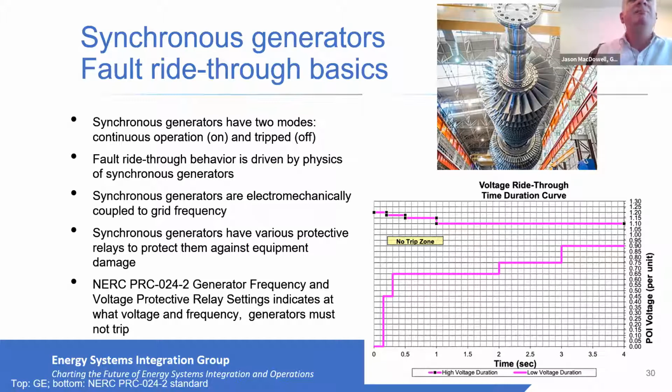So today, it's very common in all areas to have requirements during electrical disturbances to have generation remain online, ride through, and not trip. And that actually started from inverter-based resources more than 2 decades ago, where grids in Germany, grids in Ireland required fault ride-through capability.